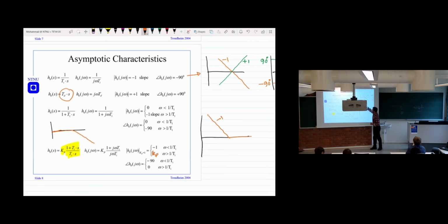So this is what we see for a PI controller. At the low frequency, or in DC, you have a very high magnitude. That gives very good characteristics for this PI controller. And when it reaches high frequency, then we see it's 1. And if you increase the Kp value, it will keep the same structure, but it will shift the magnitude, because you are increasing the value of the Kp gain. And here -1 is because we are assuming Kp is equal to 1. So this is what the characteristics of a PI controller look like.